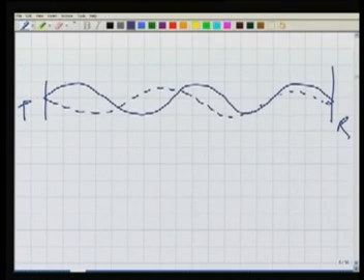That's the one which is going there, and this is the reflected one. Now we can measure the phase of the wave at any moment. For example, once this wave is leaving the transmitter here, we can measure the phase as phi 1. Once this wave is reaching again the receiver R, we can measure again the phase of the wave as phi 2.